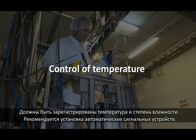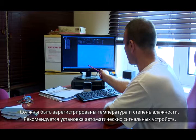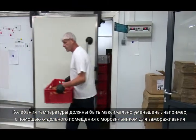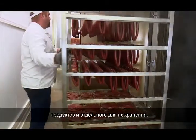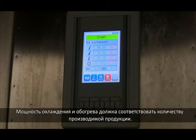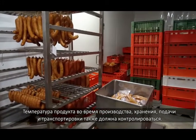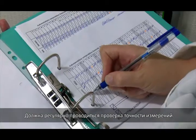Control of temperature. Temperature and moisture degree must be registered. Installation of automatic alarm devices is recommended. Temperature fluctuations must be reduced as much as possible, for instance, by using a separate premises and freezer for the freezing of products and a separate one for the storage thereof. The power of cooling and heating must be adapted to the quantity of manufactured products. Product temperature during the production, storage, serving, and transportation must also be monitored. Verification of checks of measurement precision must be performed regularly.